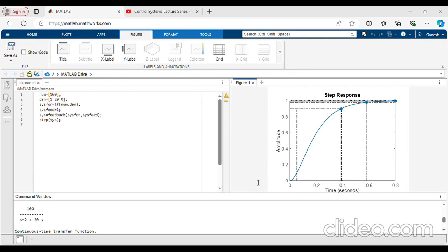Therefore, increasing the damping ratio results in an increase in rise time. That is what we have seen theoretically. Then, when you increase the damping ratio, overshoot is reduced. There is no overshoot at all now because it is critically damped. But settling time was 0.808 second, now it is 0.583. So there is a slight reduction in the settling time. It may appear that this settling time is comparatively smaller than this, but if you go for an overdamped system, probably things will be different.